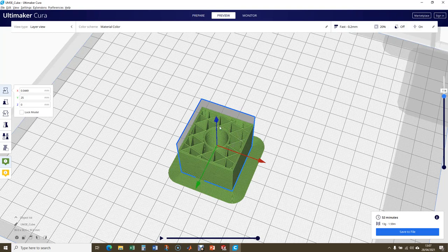So if we wanted higher strength, we could go for 50% infill or higher. If you go for 100% infill, it will obviously be the strongest, but it will use a lot of material and it will take a lot of time. And other methods of manufacturing would nearly be better at that stage. Okay, so it's this percentage infill that allows us to 3D print parts relatively quickly. But it is a trade-off between strength and speed and weight, and the amount of material we use.